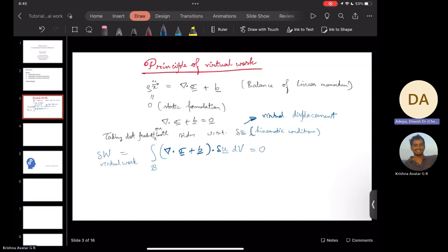We are saying that at every point inside the interior, the material points are moving a little bit, perturbed. That's what delta U means here. I'm just drawing a schematic for you. On this part we apply U equal to U naught. This means a prescribed displacement. It's a boundary condition, the Dirichlet boundary condition.